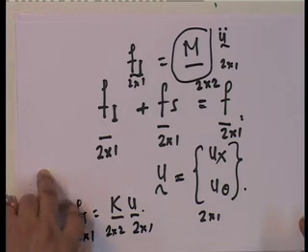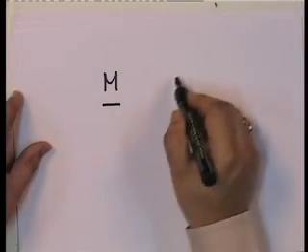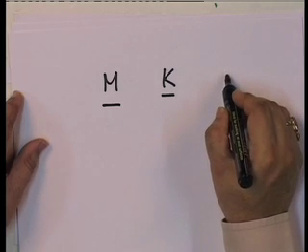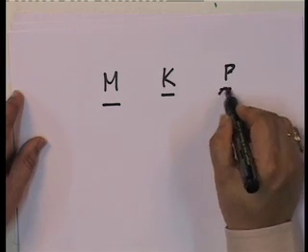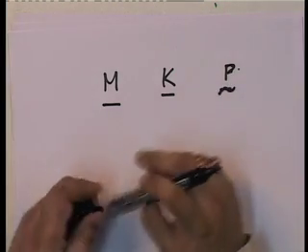Okay. So essentially, remember in the generalized single degree of freedom, we had to find out m star, k star and p star. Here what we are doing is we have to find out the M matrix, the K matrix and the P matrix, I am sorry, P vector. P vector is the load vector. And so these are the things that you have to find out in this particular case. So if you really look at it, how will this equation look? Now, this is what we need to find out.